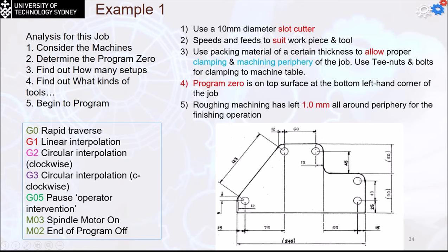In the assignment you have to do multiple cuts. You have to do the face milling, for example, the pocketing in the middle, the drilling, and the profiling at the end. Now in your case, you only have to remove 1 millimeter from the side to get the final shape for the profiling, but still you have to do all the cuts to shape the top level, because actually it's a very easy operation. I'm going to give you an example for that.